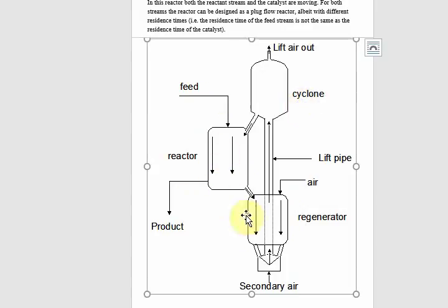So you can see in this way, we maintain nice stable operations. There's no cycling of anything here. It's not like we are waiting for anything to happen. We are constantly feeding in regenerated particles here and constantly getting a stream of product out here. So this can all operate quite nicely and steadily, and that is a continuous process. So that's a regeneration reactor. That's the solution you would apply if the catalyst particle is deactivating too quickly for the change in temperature style solution.